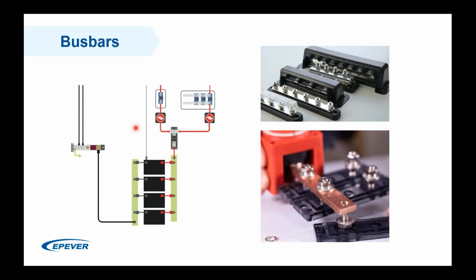If using a bus bar, its thickness should be calculated as well. It's like a cable and should tolerate the current capacity that you need in your system. To calculate bus bar thickness, simply use the recommended cable surface area and apply that to the bus bar cross-section area. You have a width, a height, and a length. Of course, you can omit the length.